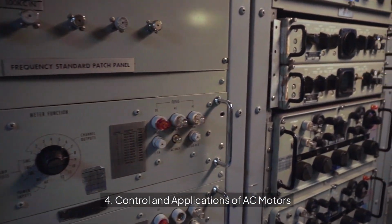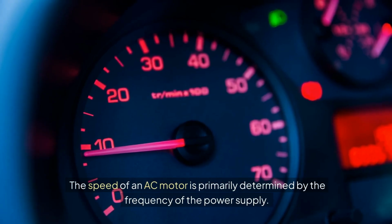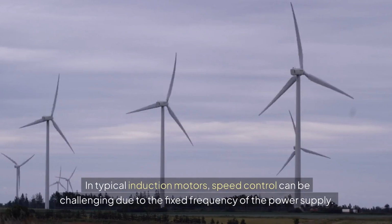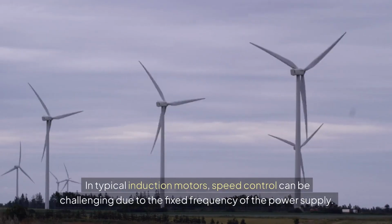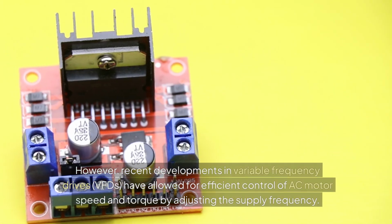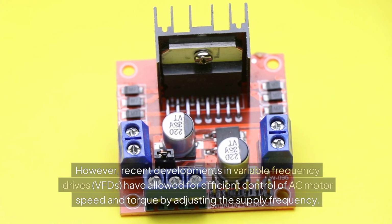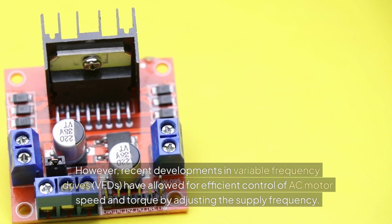4. Control and applications of AC motors. The speed of an AC motor is primarily determined by the frequency of the power supply. In typical induction motors, speed control can be challenging due to the fixed frequency of the power supply. However, recent developments in variable frequency drives, VFDs, have allowed for efficient control of AC motor speed and torque by adjusting the supply frequency.